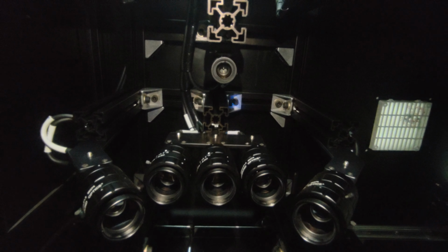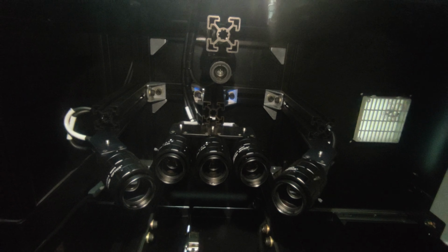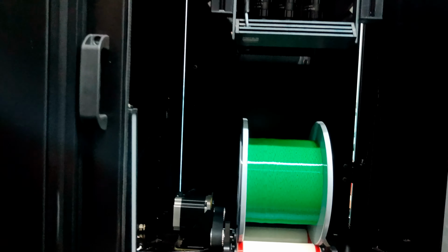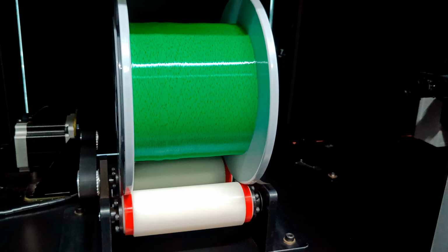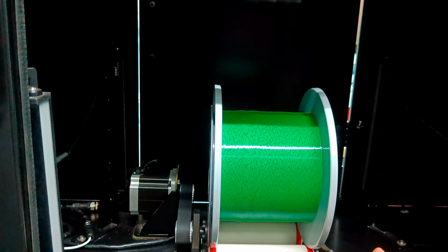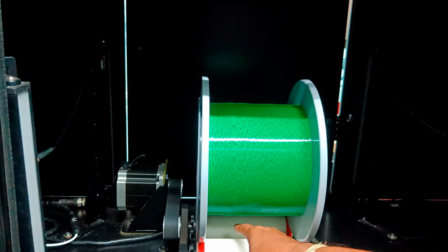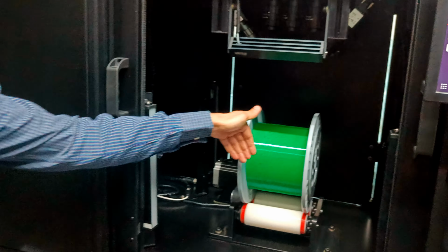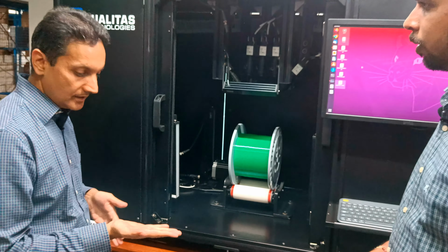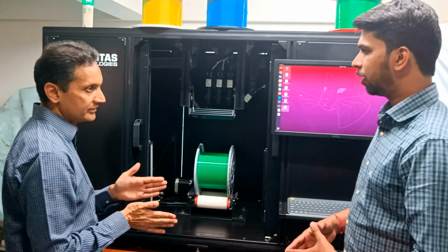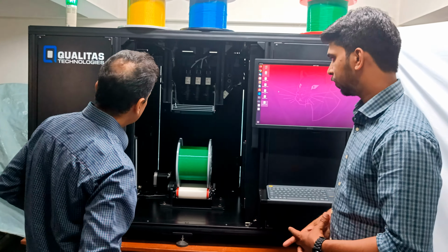So basically, during the winding, there are chances that there might be uneven winding. When you touch it, you can feel that. Yeah. Okay. So it's looking at the edge of the spool so that it's identifying any unevenness. It's very difficult to identify with the conventional method. So what we are doing is finding the profile by using a backlight. So by referring to the backlight, you can see the profile, the shadow. Got it. So there's a backlight which gives you only the profile of this edge, and you can see the edge pretty sharply, and then if there's any deviation, so if it's not a straight line, we can identify that.